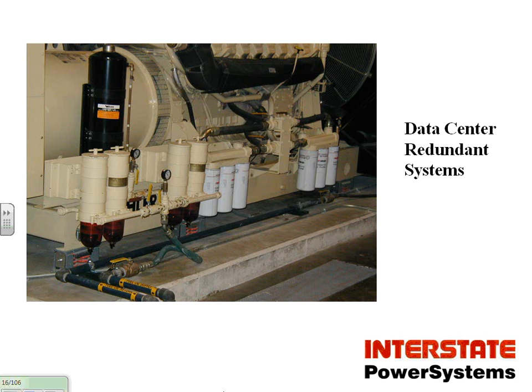We'll see some other shots. There's the fuel filters here again, and the oil filters, 2 sets. So what they do, if say we're in a homeland security situation, we're going to be running for a long time for whatever reason. These things you can change the oil filters on the fly. You can switch to this set of filters, change this set, clean them up, switch it back, and then change these. So that's the idea here. We don't have to shut down, period. And multiple sets. Again, if you have a problem with one set, you typically would size an application like this to allow for one set failure or maintenance, scheduled maintenance.